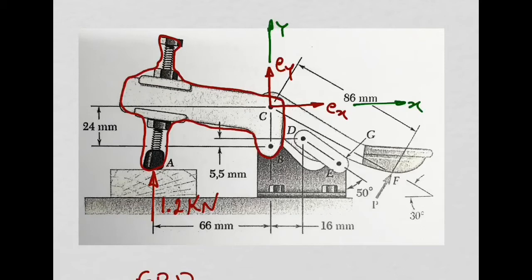What do you think? It is, right? Otherwise this would not be a hinge. So rotation is allowed, which means whenever the motion is allowed, we do not include a reaction there. In that case, that reaction would be a moment, but because rotation is allowed, we don't have a moment as reaction. So these are the only two reactions we will have at point C. You all agree with this or not?